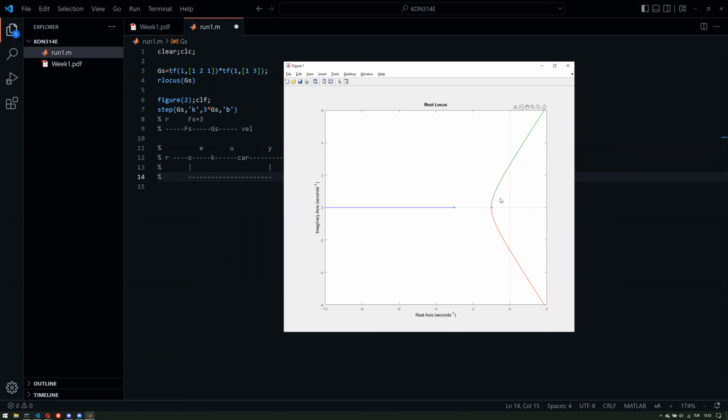So therefore, these 2 poles here will determine the behavior of the system more and more. They become closer to the j omega axis, and at some point, we will cross the j omega axis, and it will become not stable, so unstable. This stability problem is an issue that needs to be taken care of if you are using the feedback loop. So in open loop, it doesn't really matter, but here the poles change their locations.